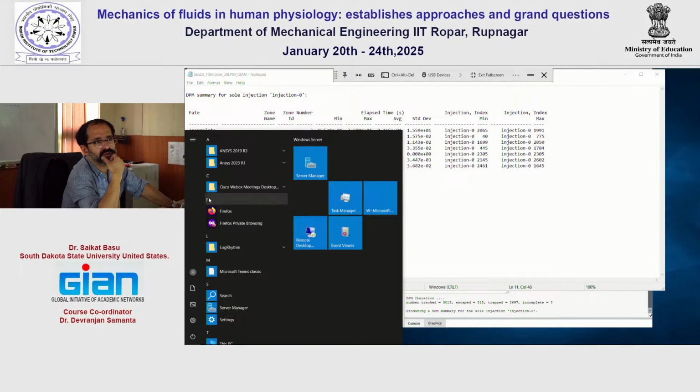No, no, no. I meant to say that ANSYS does it for you. So when you identify the surface, it directly picks up the locations of the centroids of each of the elements on that surface as the starting point for those particles. You can of course define the particle locations yourself, if you want to do that. But if you don't do that, if you just set it up as a surface injection, it looks at that surface, looks at the coordinates of those mesh elements, and then picks the centroid.